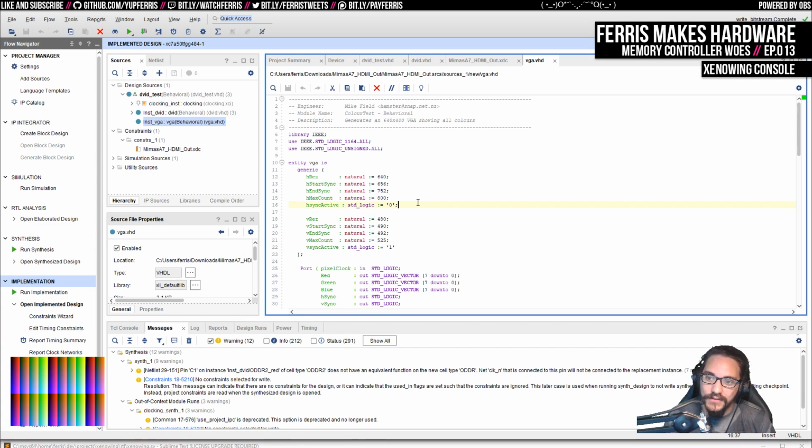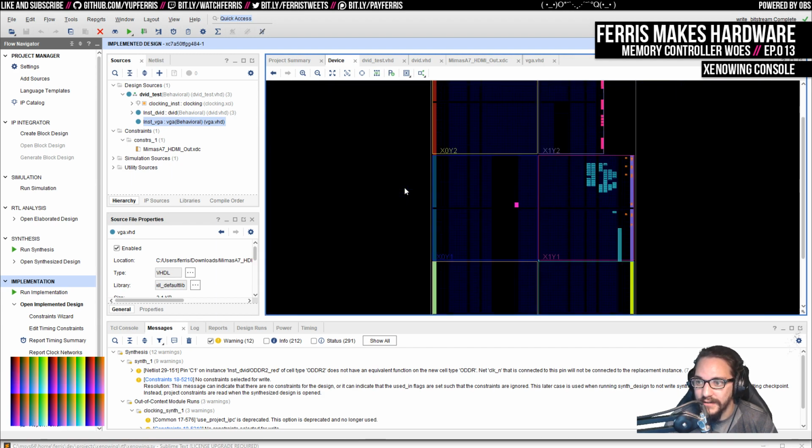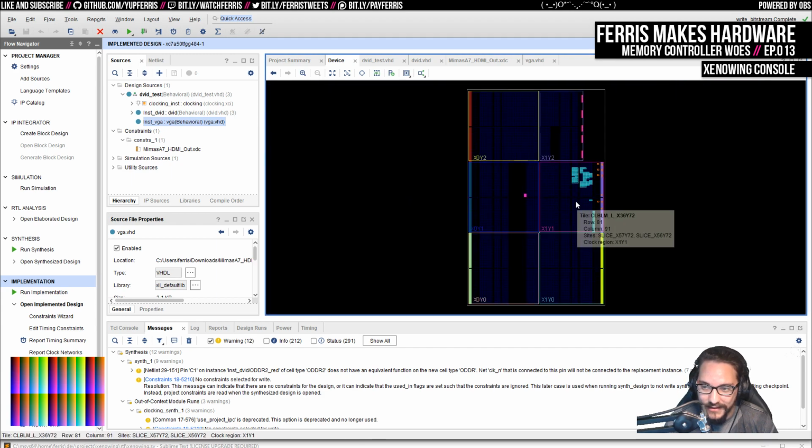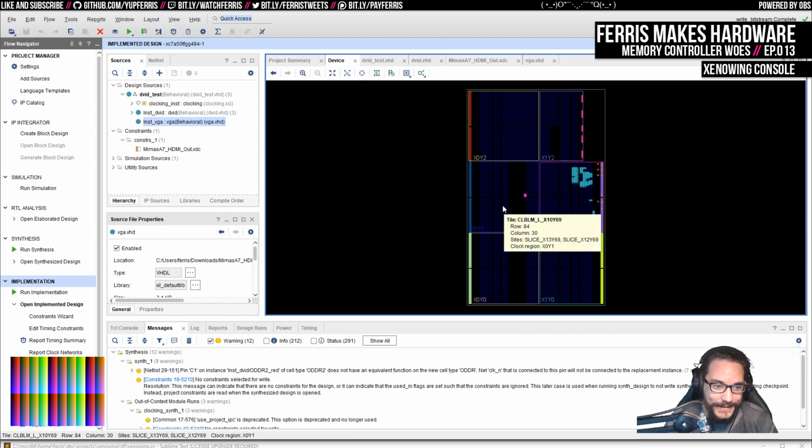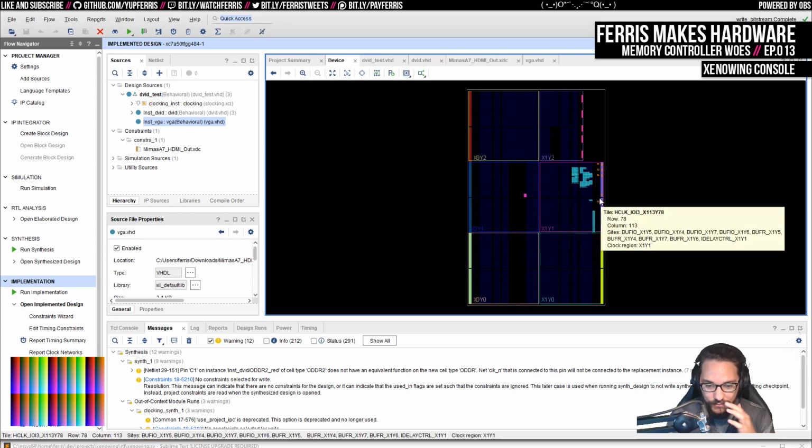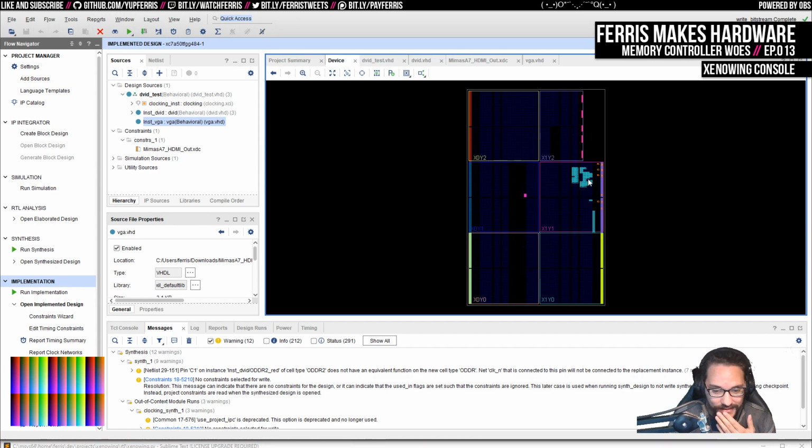Also, I don't know if we can do, I think it's called hierarchical design in the Xilinx tools, but essentially the design partitioning to say I want the memory controller in this block, and then I want the main system in this block. And then you can treat those specific units as black boxes, so that the Xilinx tools will not recompile those, which can save a lot of time.